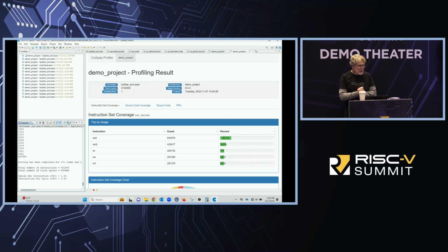So what we're going to do is just a simple branch prediction. It's so simple. All we're going to do is, every time I have a jump that I can determine in the decode stage, I'm going to do the jump in the decode stage and not wait till the memory stage. The nice thing about the jumps is they're non-conditional.